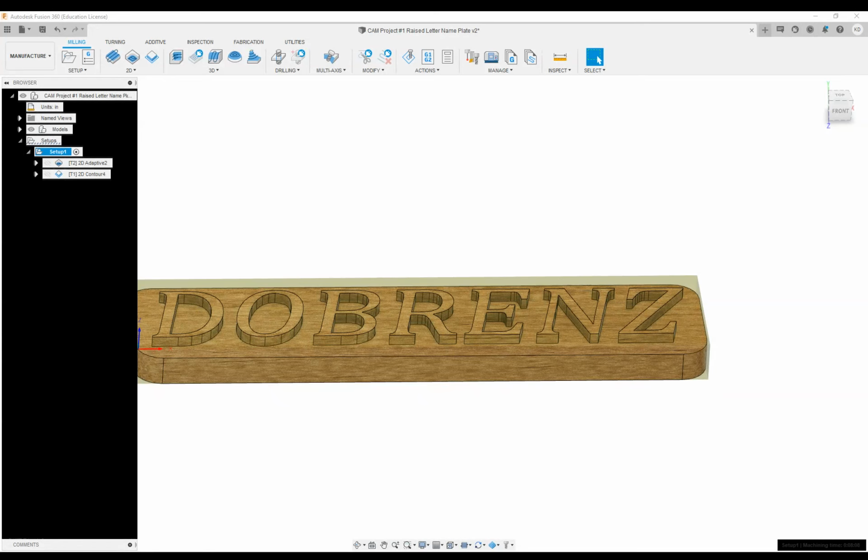What's most important here is that you understand what exactly this G-code is. For my machines, I use the thumb drive shuffle, so I will save this to a thumb drive and then take that thumb drive over to my machine and load my program that way. But this is the CAM post. This is what the computer knows how to read and execute to a CNC machine and create the product that you want. So through this series of videos, we've gone all the way from the design to spitting out G-code.